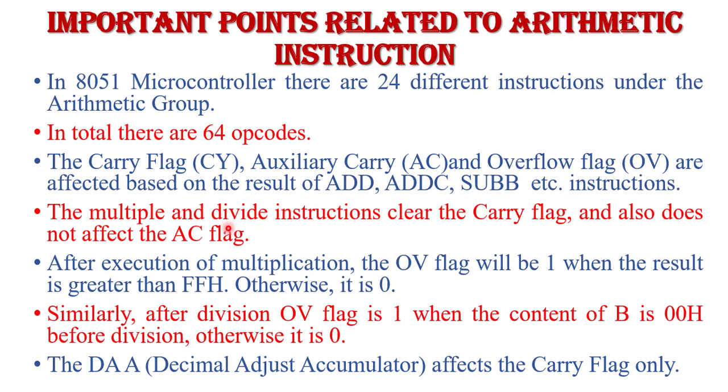The multiplication and division instructions clear the carry flag and do not affect the auxiliary carry flag of the PSW flag register. After execution of multiplication, the overflow flag will be 1 when the result is greater than FFH, otherwise it is 0.